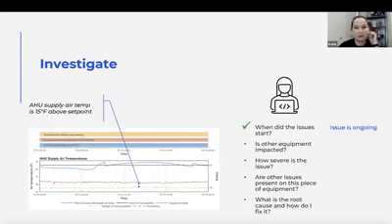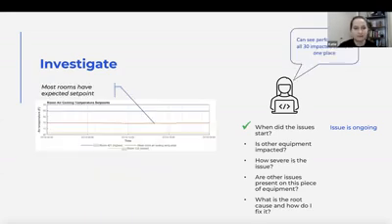So we investigated a little bit more. We looked to see when the issue started. In this instance, the issue has been ongoing. It's happened for a couple weeks before anything was responded to. And so we look at that first one that shows our supplier temperature, and we're 15 degrees above set point. So if I was a technician looking at my BMS in the morning, maybe I would see that as a problem, but just depends on what I had going on that day. But I'm going to look and see how much of an impact this has on the zones that I am providing so much warm air.